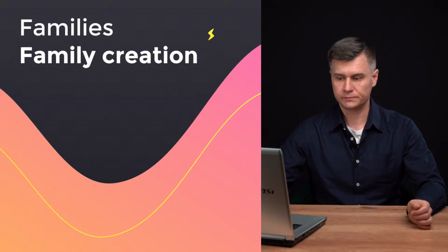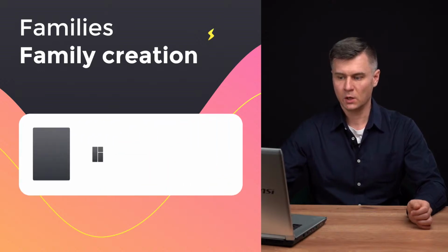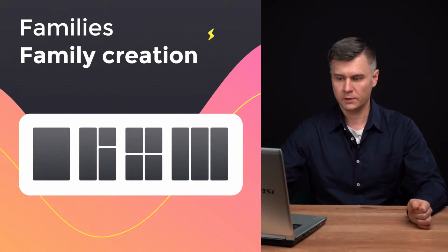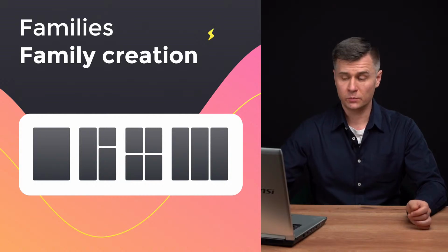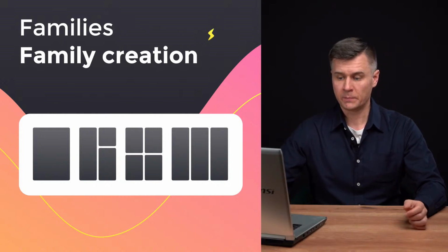When speaking of family creation, we need to mention the following creation capabilities: creation of several family templates, all form elements and the void form. These are base elements for creating family geometry. Family geometry combination, which is a Boolean operation on form elements. Openings in host elements in a family file. Dimensions and reference plane elements.